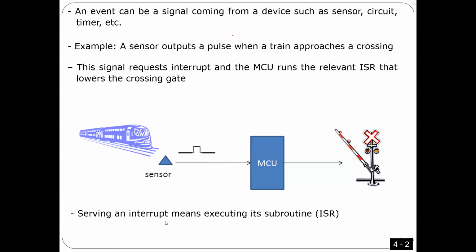The term you are using, guys. So now you should understand. We have what we call interrupt request, and we have a term serve the interrupt. Interrupt request. You are requesting the interrupt, right? You request by the event. Every time there is a signal this way, this is the event. So the event is going to request the interrupt. When I execute the subroutine of this interrupt, now I serve the interrupt. What I'm saying.